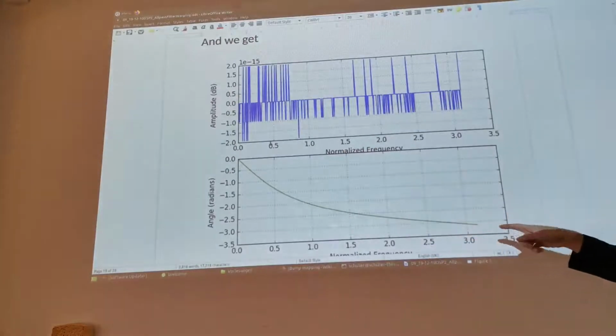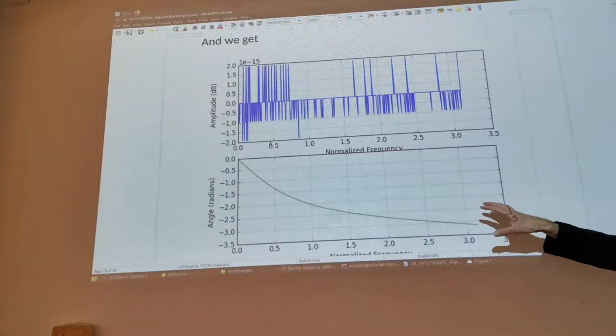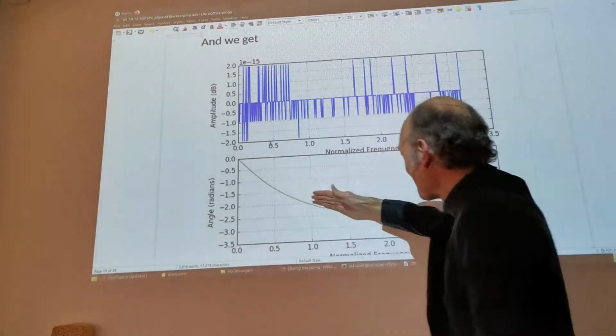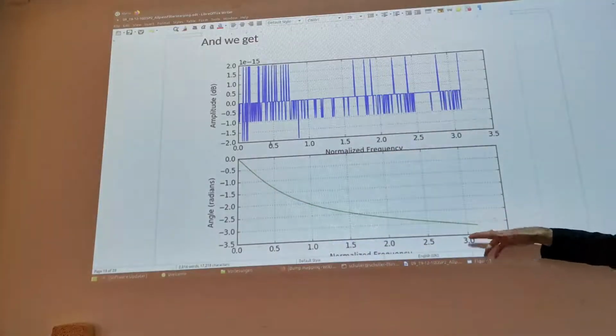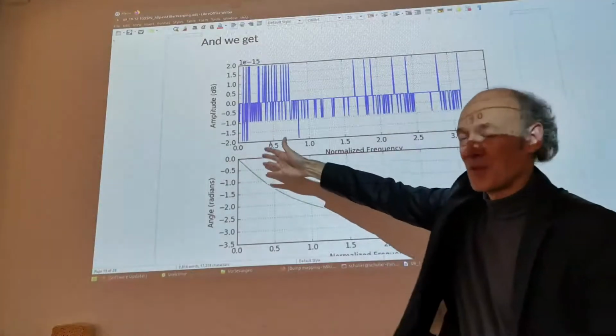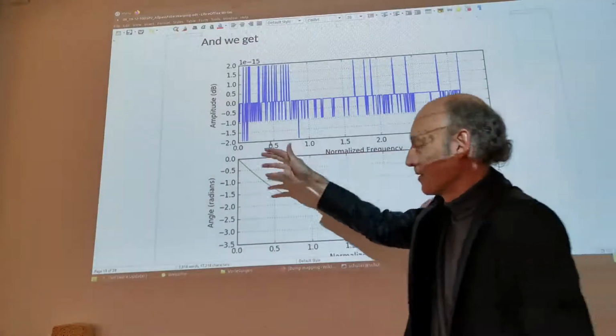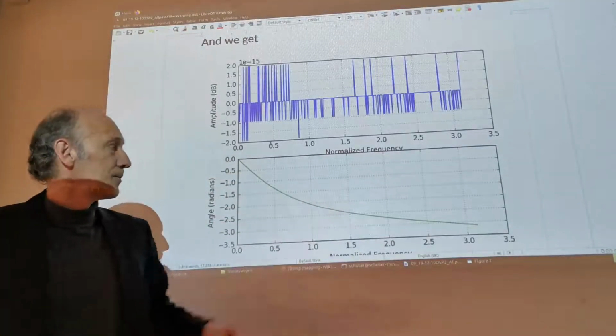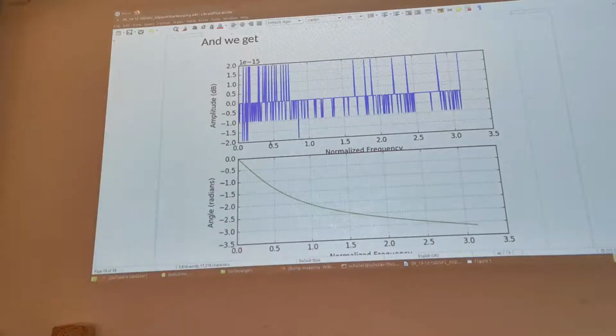And here you can also see the phase looks quite different from our fractional delay filter. First, it doesn't go as far, it basically stops at pi. And then we have this clearly visible nonlinearity. It has this bow here. So it indeed looks like the closed form plot that we just saw, here for A equals 0.5. So that's a nice confirmation that our formula is right.